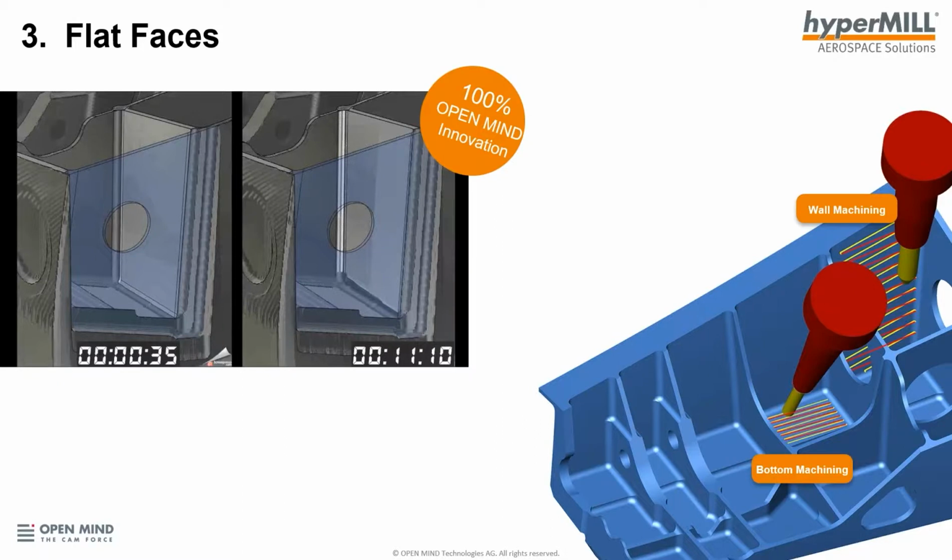So where can this be used? Well, it can be used, as I said, on flat faces and slightly curved faces, so wall machining, but you can also use it on the bottom of these pockets as well. If the taper is quite high, then you can use it for bottom machining as well. The taper is key. The taper moves the tool naturally out of the way of collision. So a barrel tool is not the same as a conical barrel tool, and people should really look at the difference, because this conical barrel tool is the key to successfully machining these types of pockets.